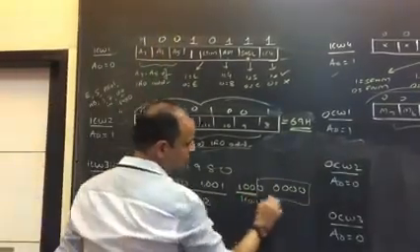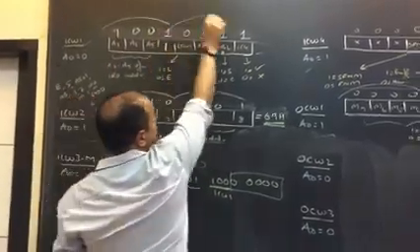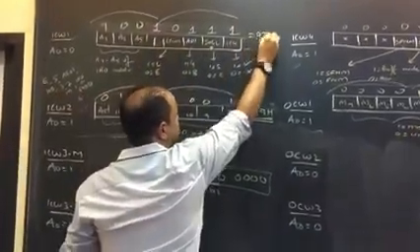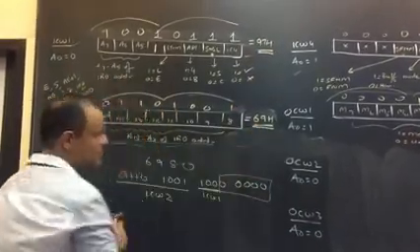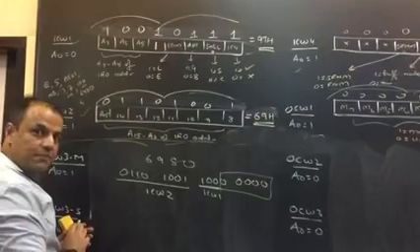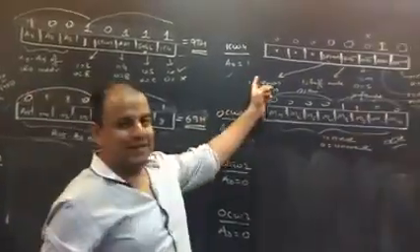These 5 bits are always assumed to be 0. Are you clear? So this number becomes 9 and 7. 97H is your ICW1 command value. 69H is ICW2 command value. Please tell me, are you so far clear? Now, ICW4.